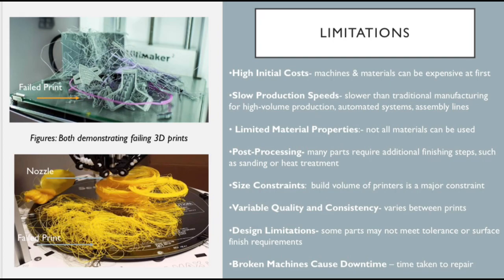There are limited material properties. There's also post-processing that has to happen. There are size constraints due to the build volume of printers, variable quality and consistency between prints, design limitations, and lastly, broken machines can cause downtime because they take time to repair.